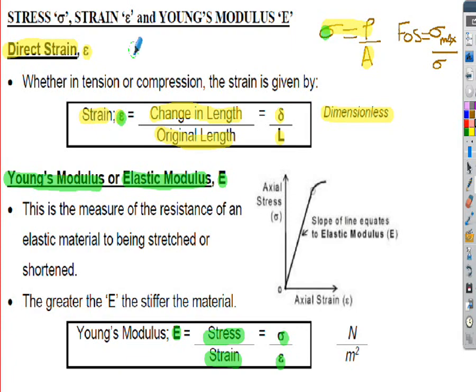And what you've got there are three equations now. It's one for stress, one for strain, and one for elastic modulus. They all relate to each other, they all interrelate with each other. So just for your reference, the E value relates to the slope of the line. You may have heard of Hooke's law before. I know some of you have come across that.